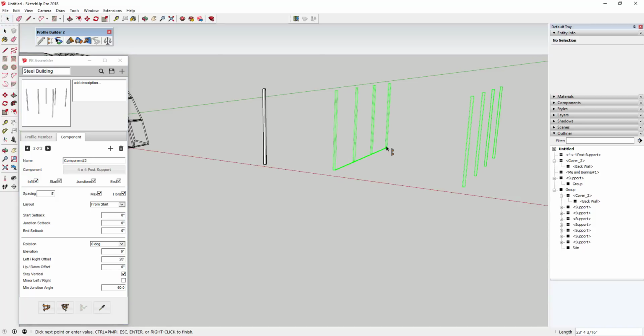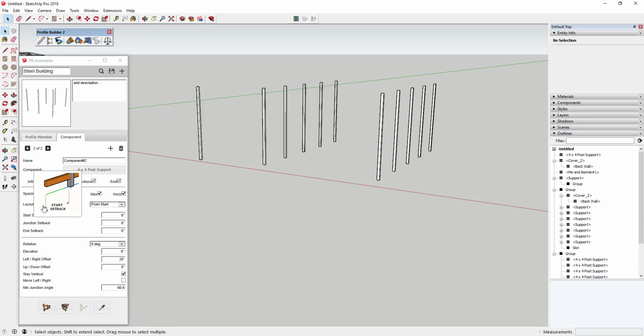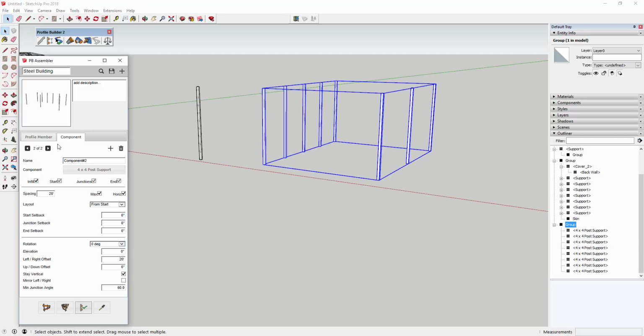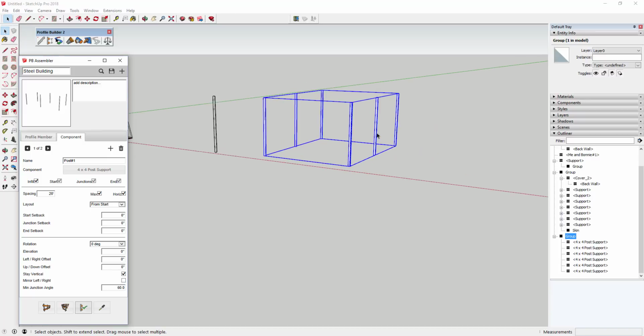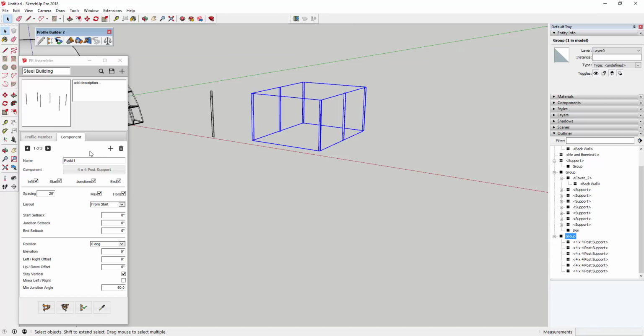So now, if I do that same thing, it'll give me a series of posts in here at 8 feet on center, and I'm actually going to adjust that to something like 20 feet. And you can go ahead and click on this object that you're creating and click Update, but for each one of those, you could set those at a spacing of 20 feet. And then just click the Update button, and you can see how that's quickly adding these in here. And so I'm going to go ahead and create one more. We'll call it post number 3.